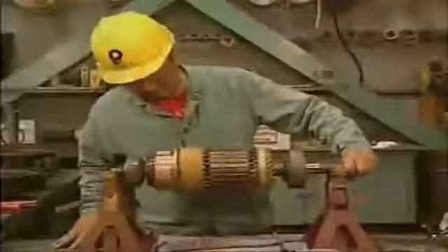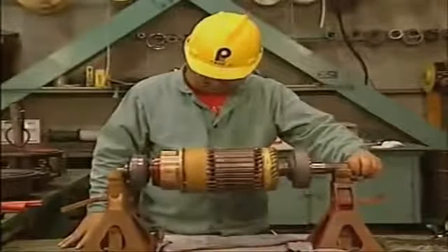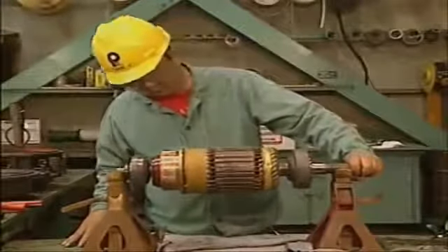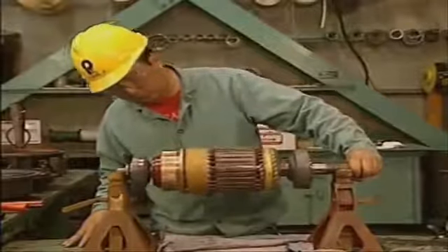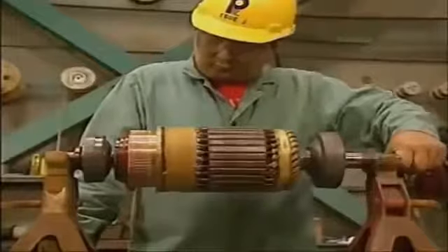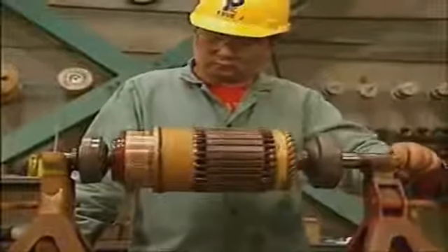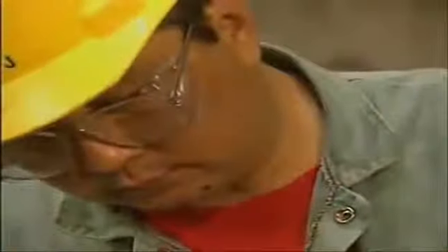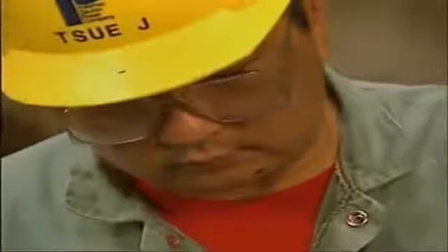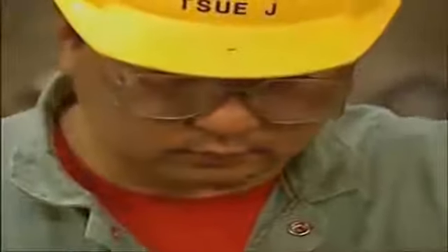ground. Next, the armature winding should be checked to make sure that there is no evidence of solder being thrown out of the risers. The presence of solder is usually an indication that the commutator has been overheating, either because of a motor overload or because there is armature winding damage.